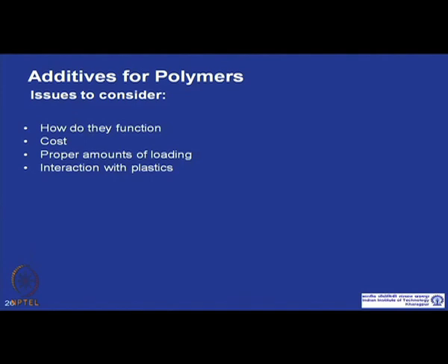Proper amount of loading; sometimes these additives function only for a particular level of loading. Too little loading might not bring about the advantage which the manufacturers are looking for, and too much addition of the additive might destroy the polymer itself. Obviously, the cost of the formulation will go up. So, the optimum loading of the additives is what is required, and we must know the interaction of the additives with the plastics.